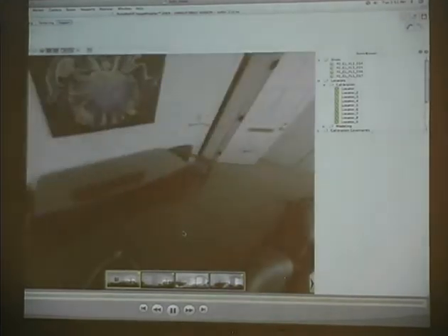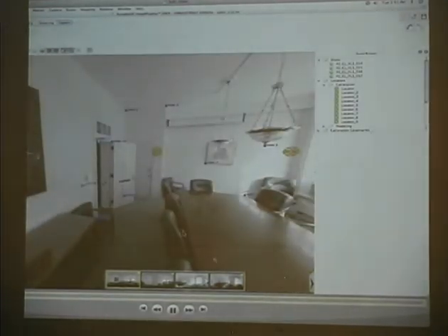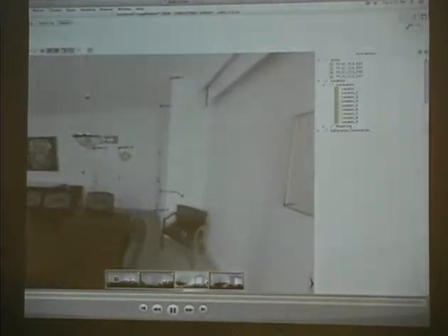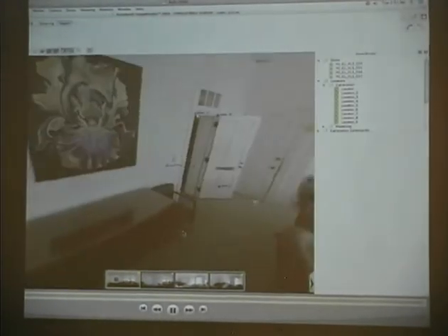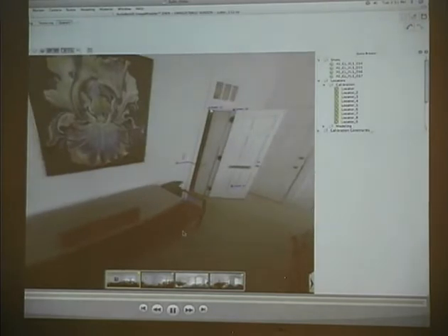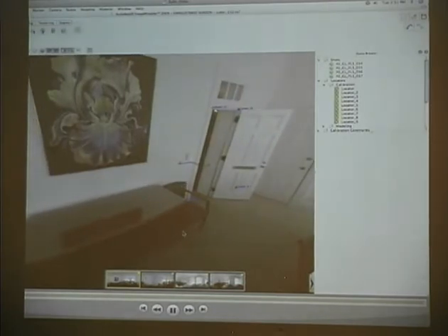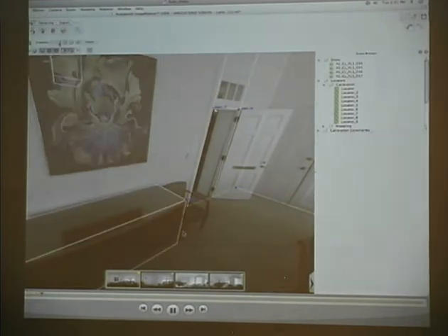We have 4 scans within that room, represented at the bottom. Those blue dots with the text are locator nodes. We usually look for corners or doors that are square, where we know the dimensions and that show up in every camera shot. We place points in the corner in each camera's perspective, and the computer will process how to match those up.